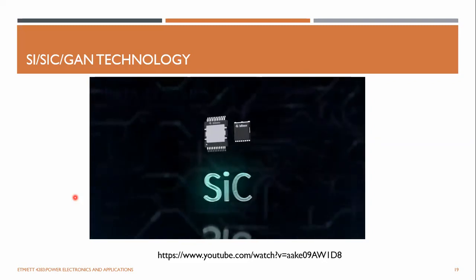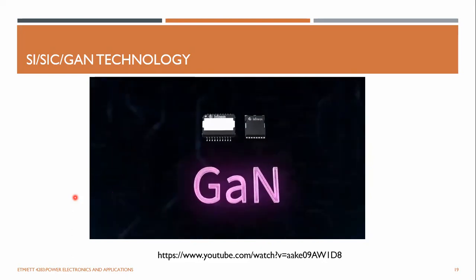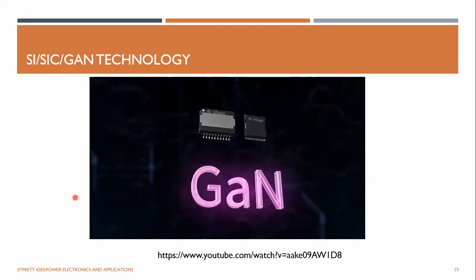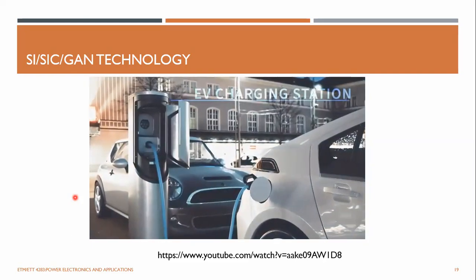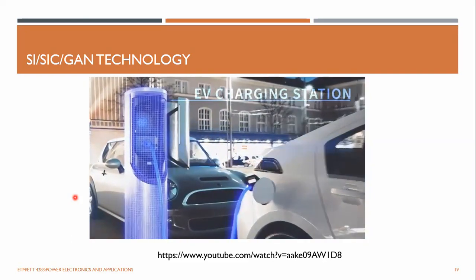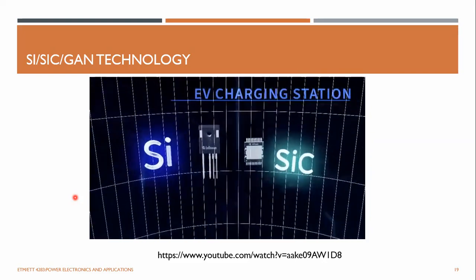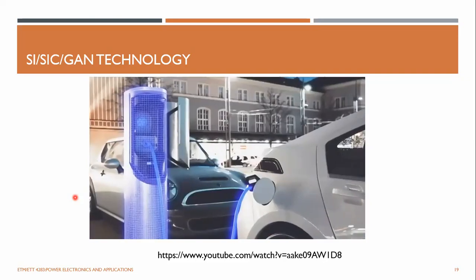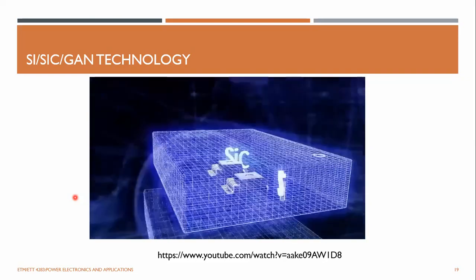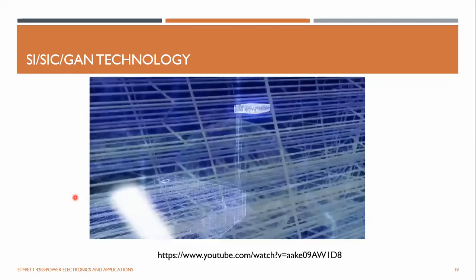Wide bandgap materials complement silicon solutions, pushing the envelope of power efficiency, size, and weight reduction further for even higher levels of performance and enabling new topologies. Silicon carbide can withstand high temperatures and harsh environments. In addition, the possibility to use standard drivers with it makes silicon carbide an easy-to-use option for improved performance compared to silicon.